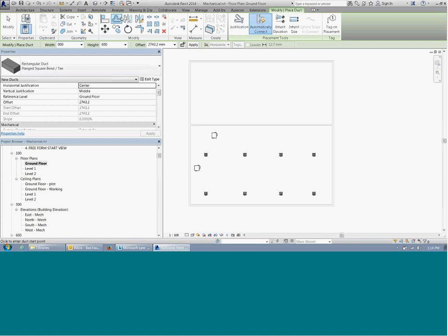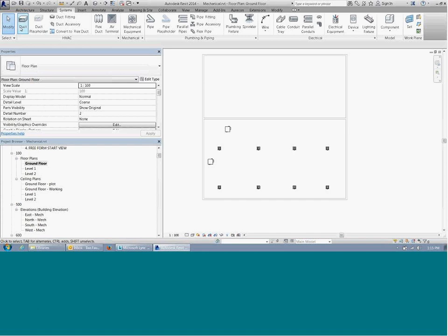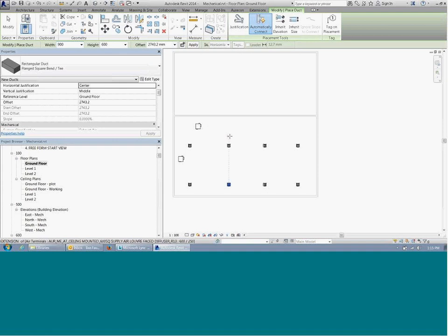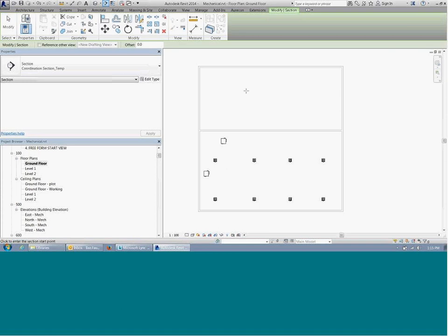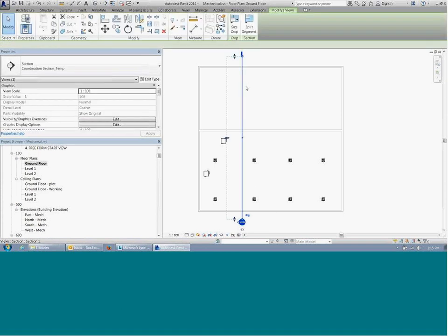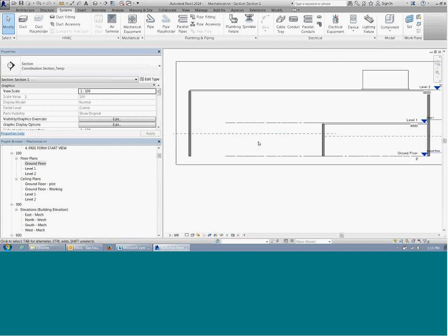Right, I can understand. Our MEP systems are located under the Systems tab. So you've got your HVAC, which is ductwork, duct fittings, air grills. Then you've got a mechanical sub tab. Then you've got your plumbing, electrical. I went through ductwork last week. So if we were to draw a duct on this plan, first good practice is to get a feel for the project and what ceiling heights we're working at.